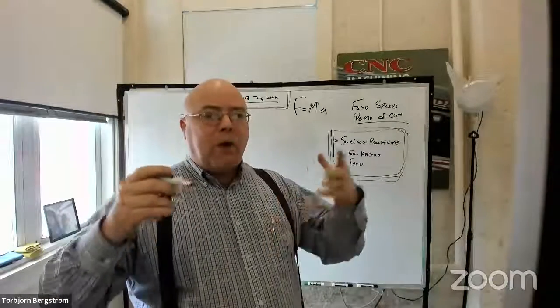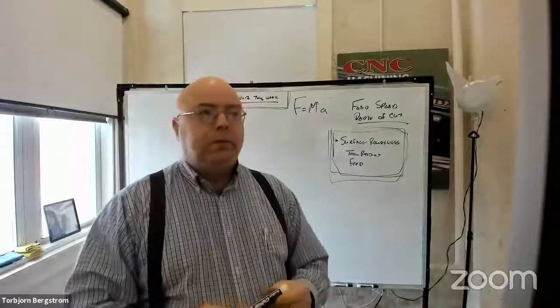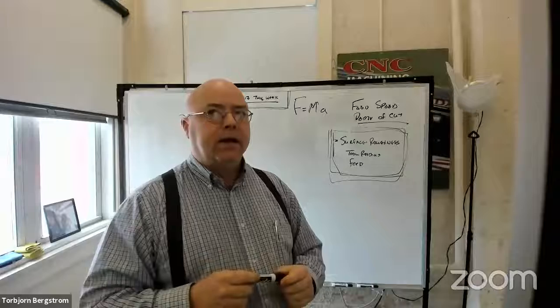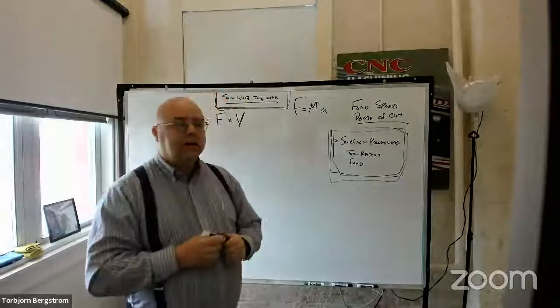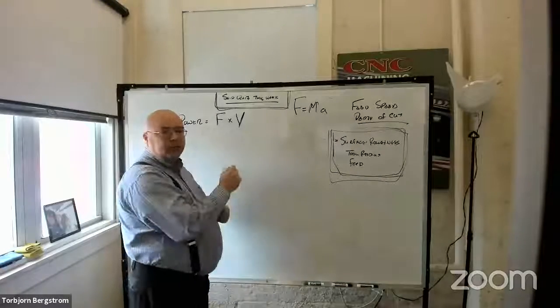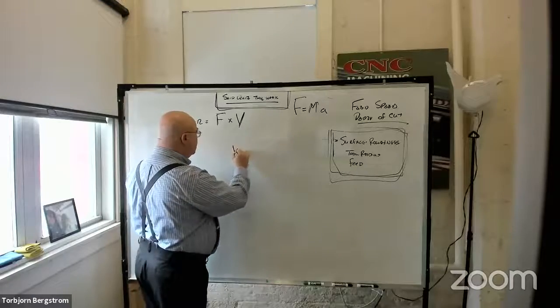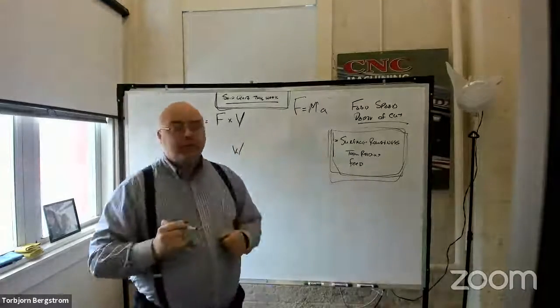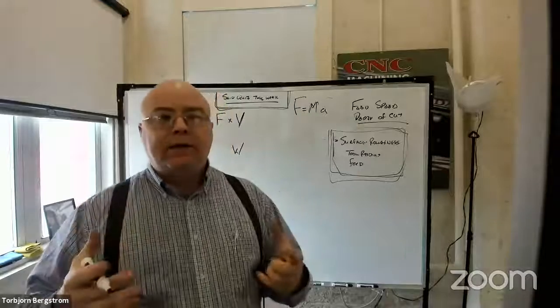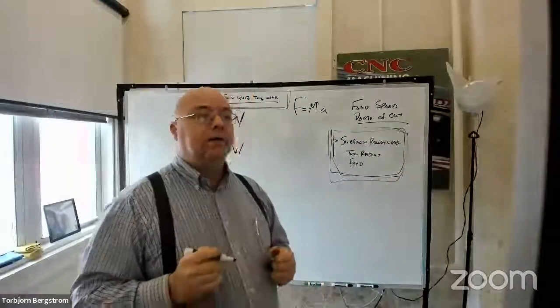What will impact how much power it takes to cut material? And we talked about that, I think, a week ago today. Tool sharpness? The sharpness of the tool. We call that W. What else will affect how much power it takes to make the cut? Hardness of the material you're cutting.